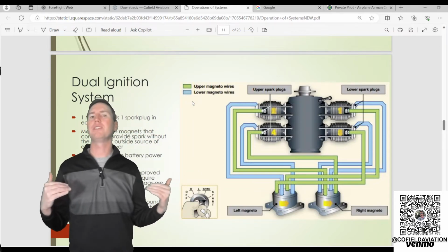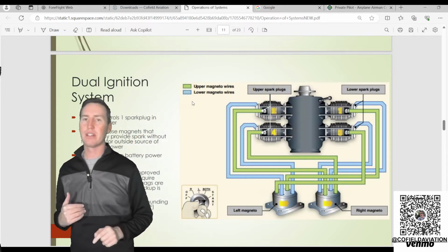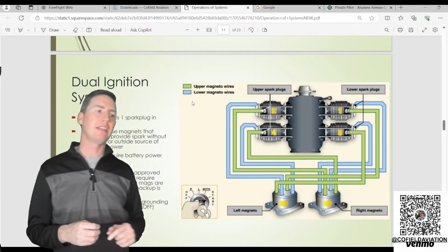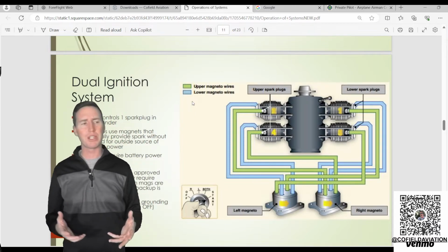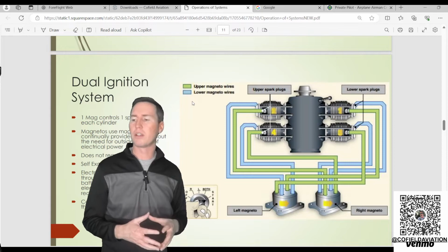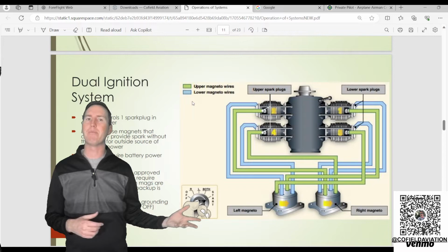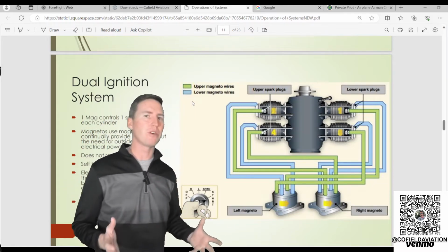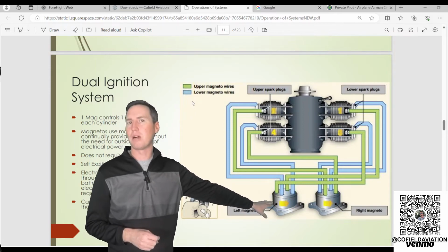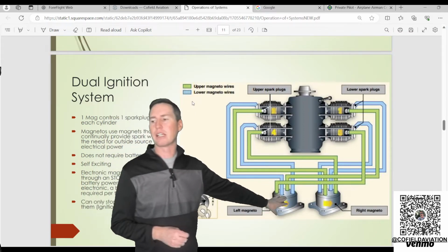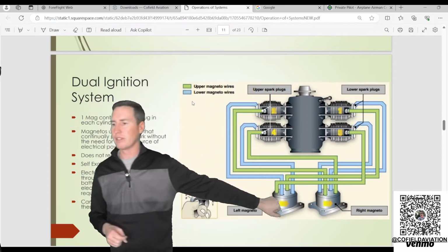Now, in our 172 model, November 61651, one of our mags is electric. The electric mag is a lot more fuel efficient. However, the FAA will not allow both mags to be electric unless you have a battery backup. Right now we don't have that in ours. The left mag in our 172 model, 61651, is an electronic SureFly mag, and the right mag is just your standard magneto.